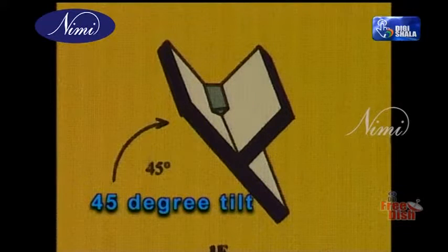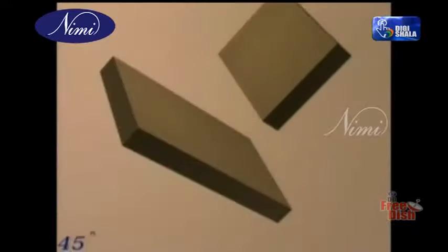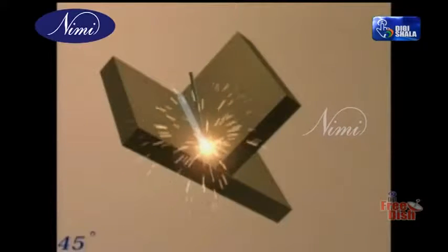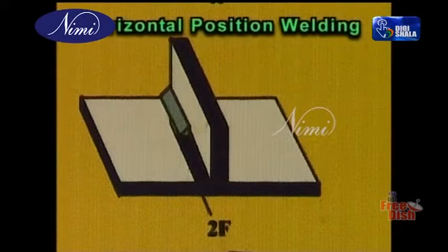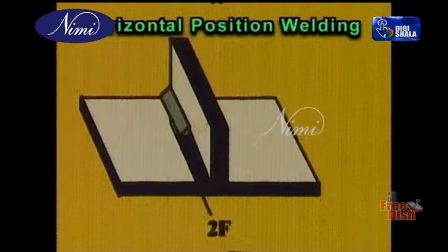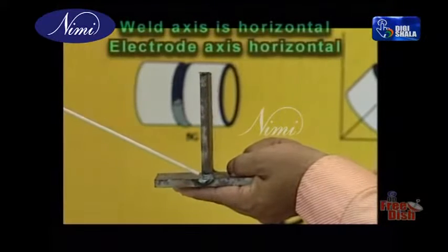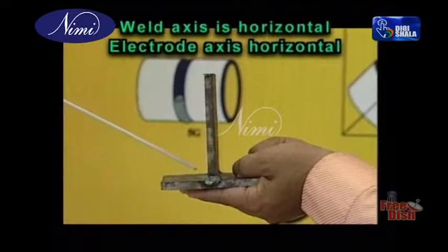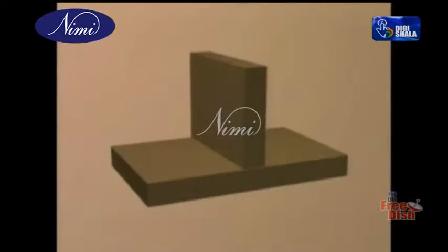Now, in 45-degree tilt, the welder is going to weld in the downhand position. Now, the next position is called 2F. 2F is called horizontal position welding. Now, the weld axis is horizontal and the electrode axis is also horizontal, and we are going to weld the joint like a fillet weld. So, this will be called 2F horizontal position fillet welding.